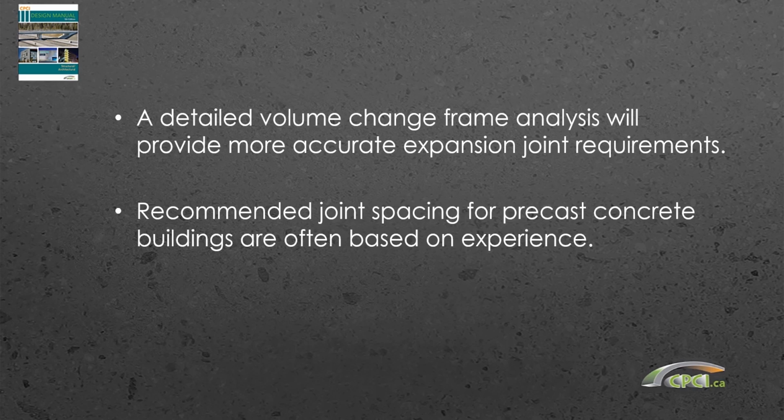Joint spacing is sometimes determined based on experience with a particular type of structure. I know PCI in the United States, although they would potentially have different climatic conditions than in Canada, has some documents permitting expansion joints in parking garages that would probably exceed the value coming out of our CPCI design manual table. So it all needs to be looked at and engineered, and definitely Chapter 2 can provide some very good guidelines as a start in looking at your recommended spacing of expansion joints in a structure.